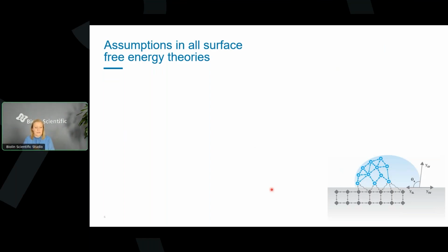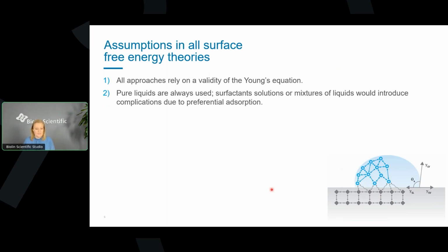And just to remind you a little bit, since we are typically using static contact angles to calculate surface free energy, independent of the surface free energy theory, you typically use static contact angle to do the calculations. There are certain assumptions that we need to make to be able to do these calculations. And the first one of them is that all of these approaches really rely on the validity of the Young's equation. So the Young's equation is the basis of the theories.